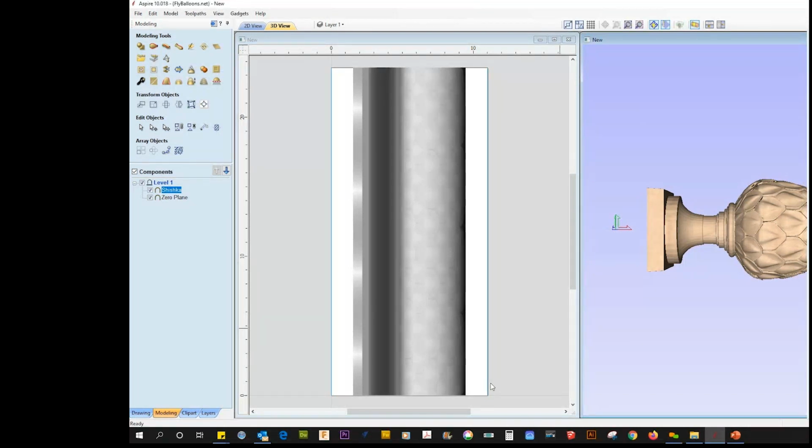And then the Z-level roughing, that means it will rough in the Z by levels, which Ted pointed out. In the new version of 10, I've noticed that it actually added order, which is level by level, and you have depth first. The level by level, it will continue to rough until it reaches the pass depth that is set by the bit.